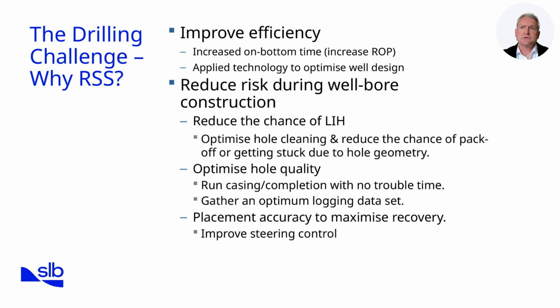Rotary steerable systems were developed in response to key drilling challenges faced with conventional directional tools. Traditional slide-rotate techniques require frequent interruptions to orient the tool face, slowing overall progress and creating inconsistent well profiles. This process also limits the amount of on-bottom drilling time. RSS eliminates these inefficiencies by enabling continuous rotation while steering, keeping the bit engaged for more extended periods and increasing the rate of penetration. Hole cleaning is another concern.